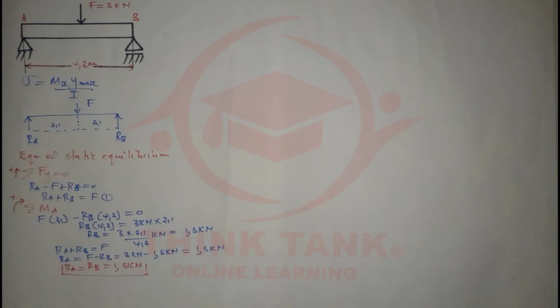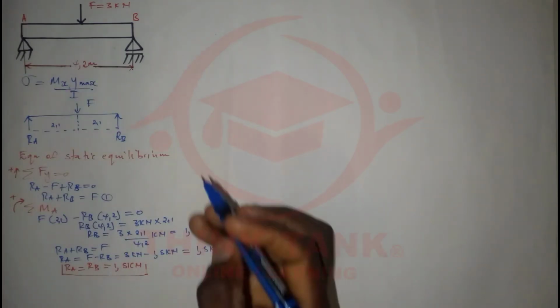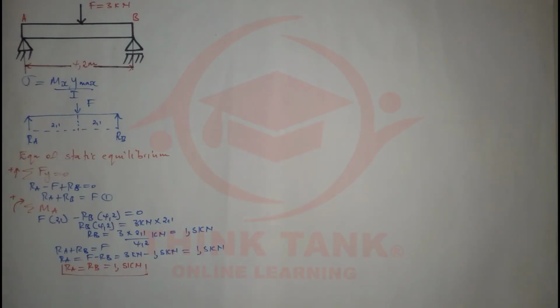We have everything right now. So now I'm going to look for Mx, the moment at the point. What I'm going to do is take a section either on the right of this diagram or on the left. You have to take it before the force or after the force.